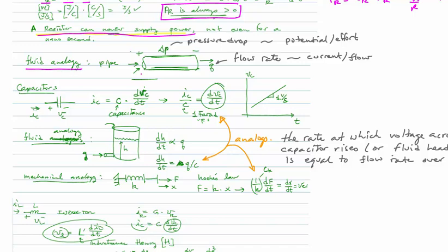So imagine you have a pipe and there's a pressure drop. There's some pressure that you apply at one end. Say the other end could just be open to atmospheric pressure, right? So you just have a spigot, water's flowing out the other end. If I apply 10 pounds per square inch at one end of the pipe and the other end is at 0 psi atmospheric, then the pressure drop across that pipe is 10 psi, and that will drive some amount of flow through that pipe.